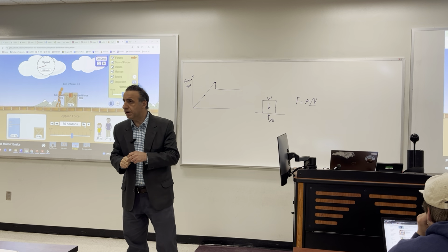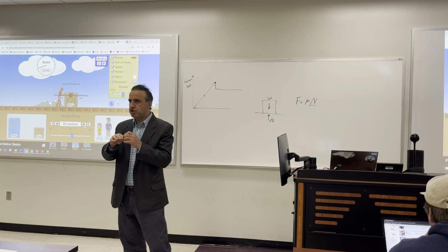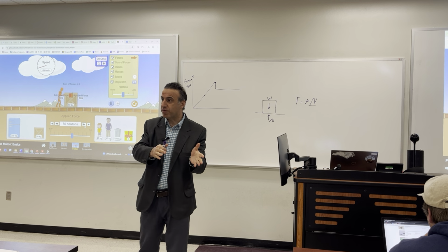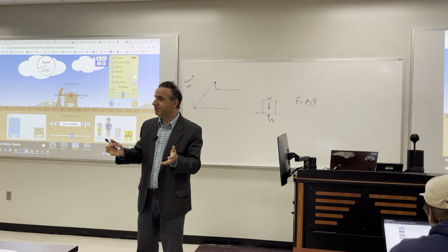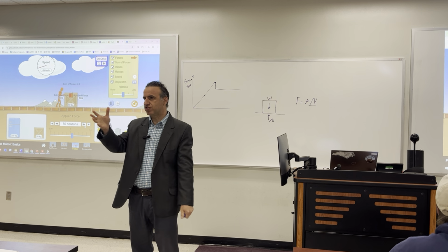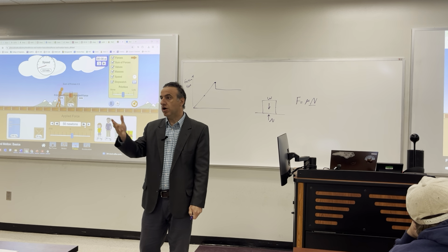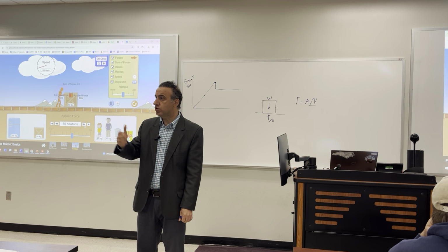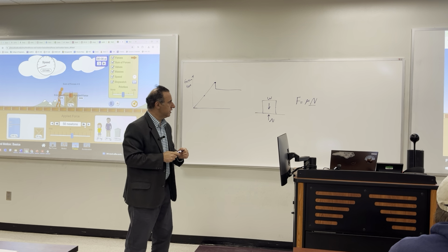Sometimes, not for this class, you want to find which friction is going to be best for your problem. Then mu might be unknown for you, and you can find it based on the friction resistance. You can choose, let's say, aluminum to steel might be good for your design, right? But for this class, we will provide that in mu.